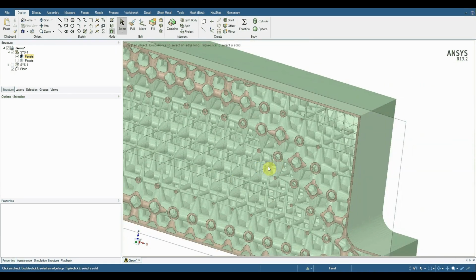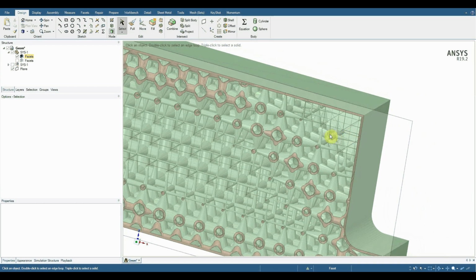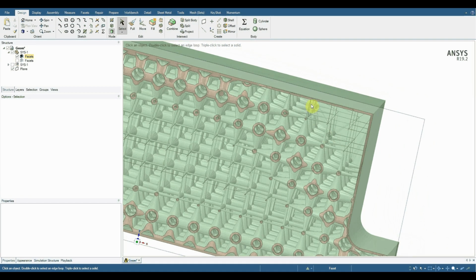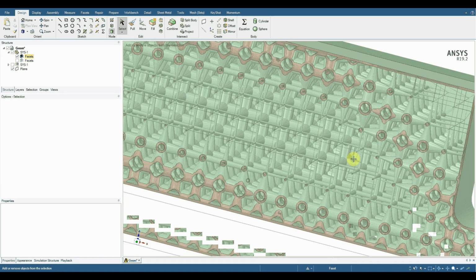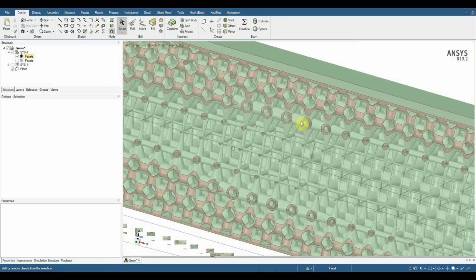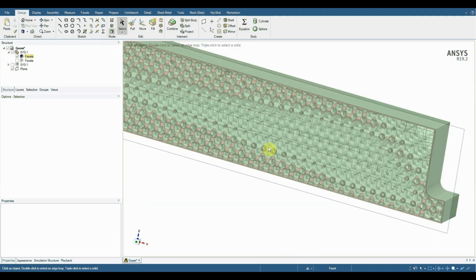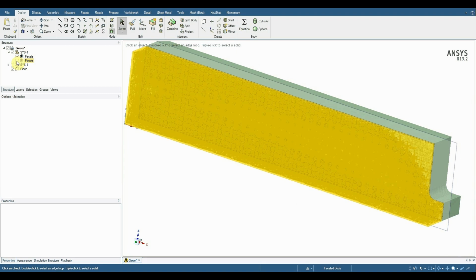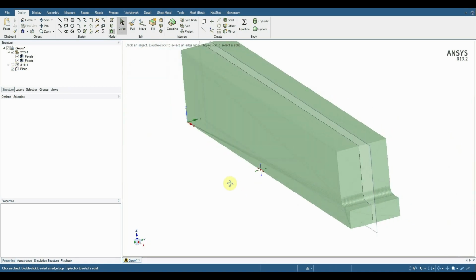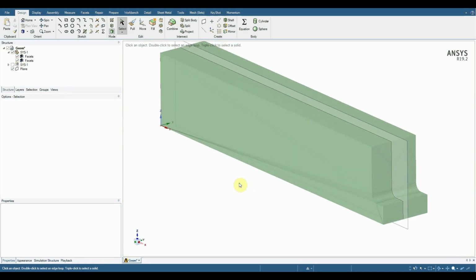Now I could change the minimum lattice density to something larger than 0, so we get a more realistic result. As you can see, we have some excessively thin members here. And these are the thicker regions, and so forth. And this is the closed part. So then you can go and take this and feed it into a 3D printer and manufacture this part.